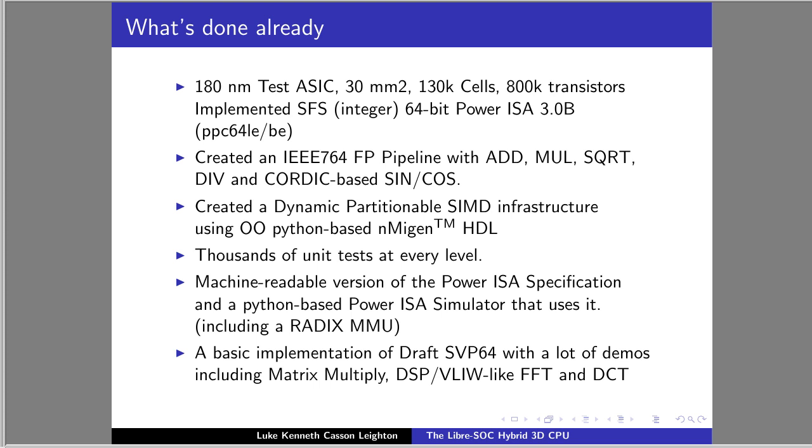The other one is the Texas Instruments DSPs, the TMS320 series, which is a VLIW-like instruction set where you can put up to 14 primitive instructions into one big VLIW-like instruction, one of which is a decrement counter and stay on the same instruction loop.